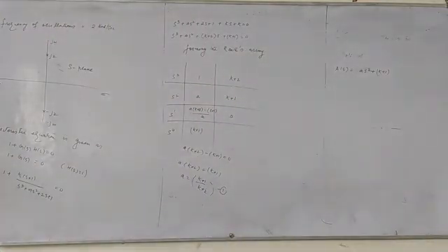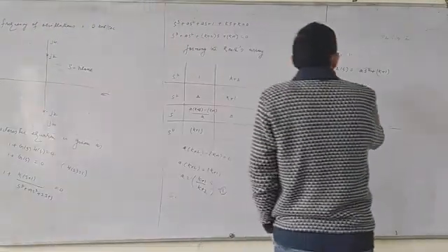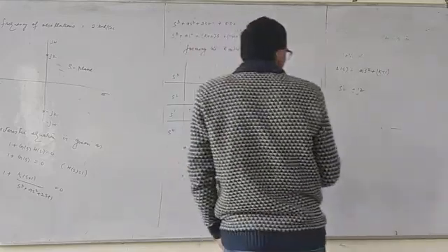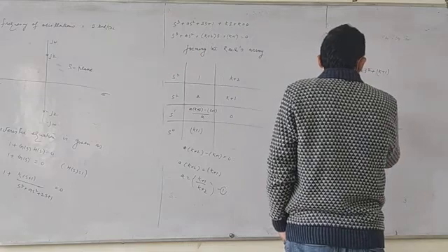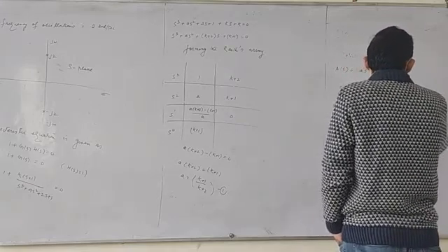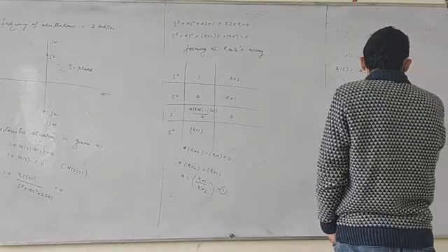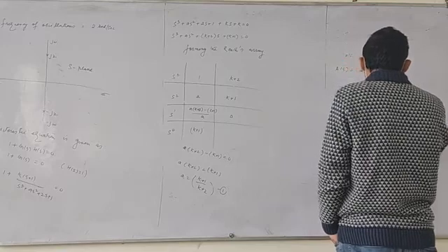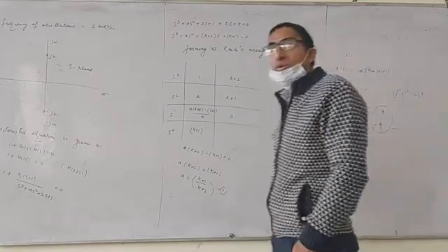Now what will happen? What are the roots of the auxiliary equation? The roots of the auxiliary equation are the frequency. Also we know that the roots of the auxiliary equations are the frequency of oscillations. Hence s will be equal to, what was given? Plus minus j2. So s² will be, if we take the square of plus j2, plus j² under root of 1 minus... the square of 2 gives minus 4. If you take the other one also, the square of minus j2, minus minus will be plus, this will be minus 4. From both sides you are going to get minus 4 for s².